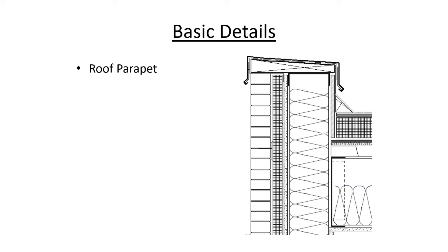Here is the roof parapet. We see that the exterior load-bearing steel framing is framed in a balloon type fashion, where the roof members, which are common C joists, are tied in through a rim track tied to the back flange of the studs. We can see cavity insulation fully filling the stud cavity.